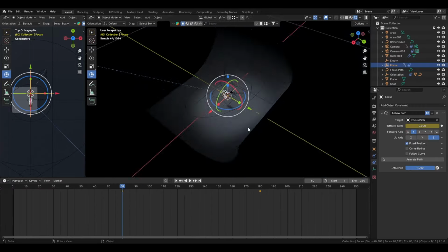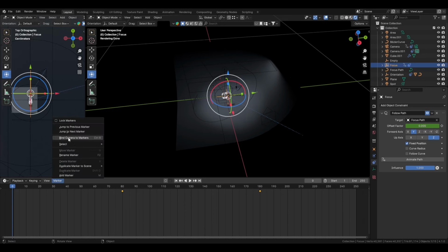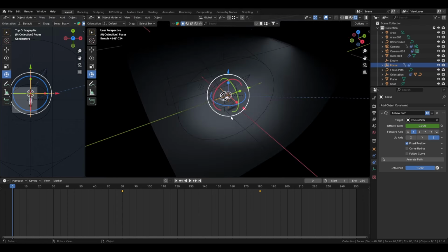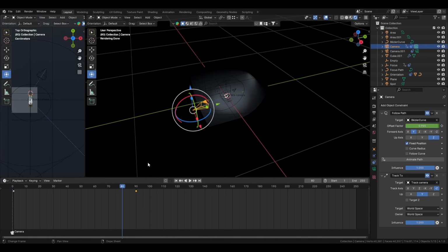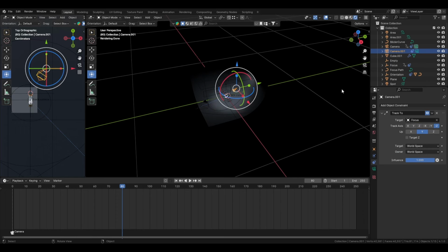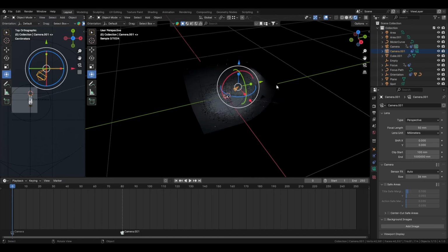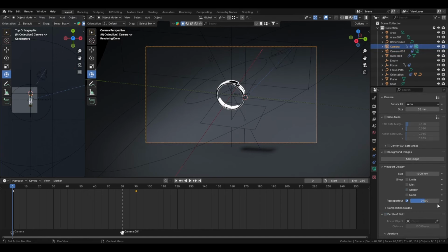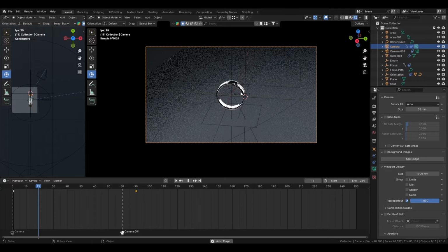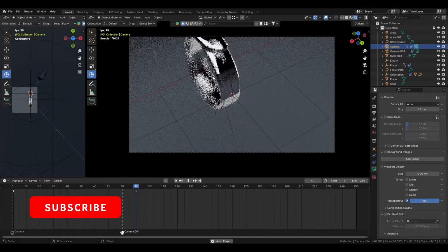And the great thing is, because we have the other one which is selected, which is turning up to frame 80, we can here do a marker and say bind camera to marker. So actually it's going to bind the one which is selected. So you want to select the first one. So you say bind camera to marker, and then at 80, because the others start moving at 80, you can select this one, make it your active camera, and then say bind camera to marker. And so now if you look, press 0, and you add the passepartout also here. Oh, okay, I need to select this one, and I'll put this here. So now if I play the animation, you see that it's going to move like this, and then go there, and like this.